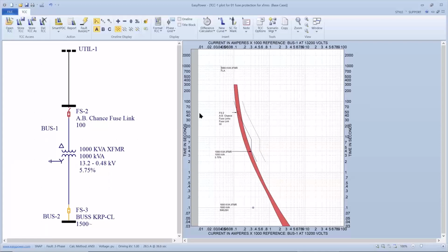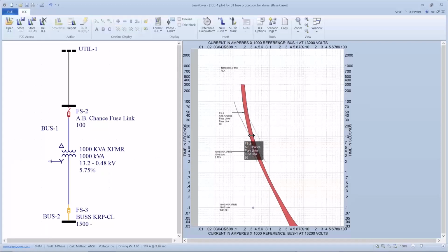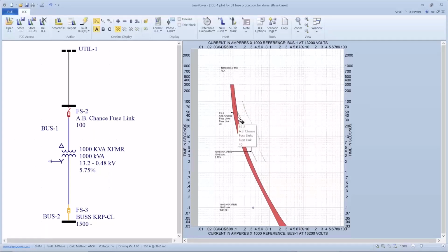Now, if I have primary protection and I have a hard fault or hard ground in my transformer, and I'm depending on this fuse to protect against a ground fault, then I need to be below this 58% derated curve because of the difference in phases. So in reality, I really want my fuse to be positioned more like this so that I have guaranteed protection for 100% duty, frequent fault, and I have protection for a single line to ground fault on the secondary.